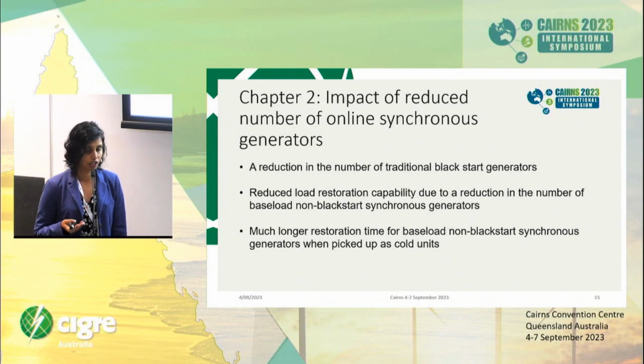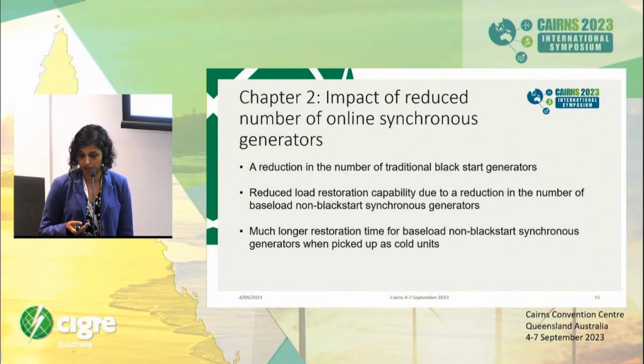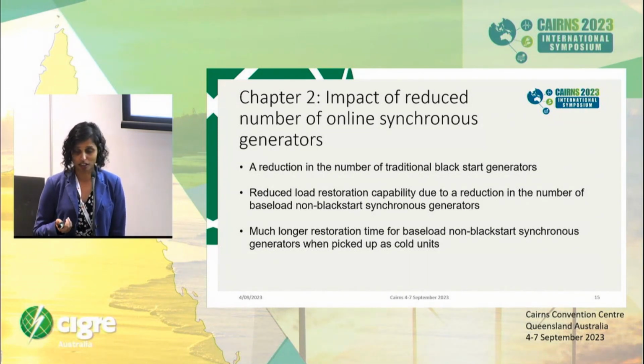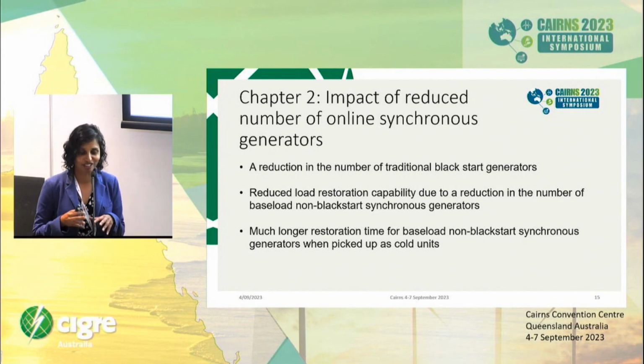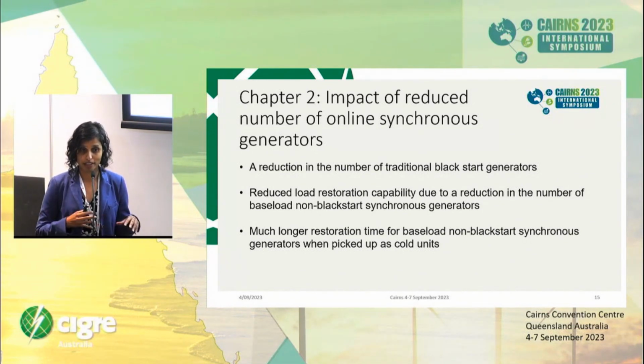And this also reduces the number of baseload non-black start synchronous generators that have that important role in supporting energization of lines and picking up load. And that could reduce the load restoration capability, which may also in turn, unfortunately, make the restoration time a bit longer, as well as the fact that traditional synchronous generators may not be starting from a hot state, they may be starting from a cold state. That will increase restoration time because you're talking about tens of hours of restart for these traditional generators to start up from different states.